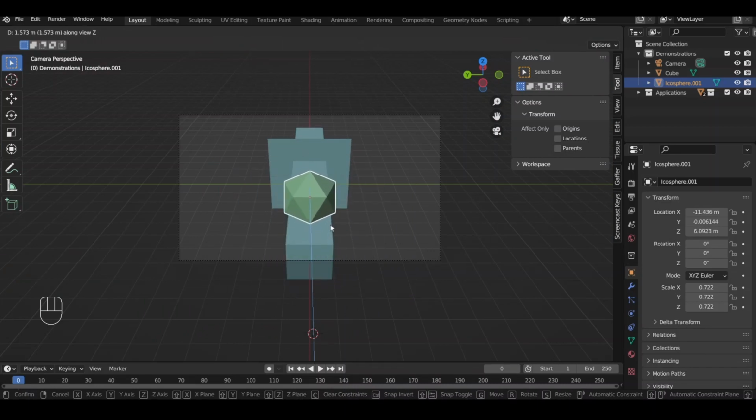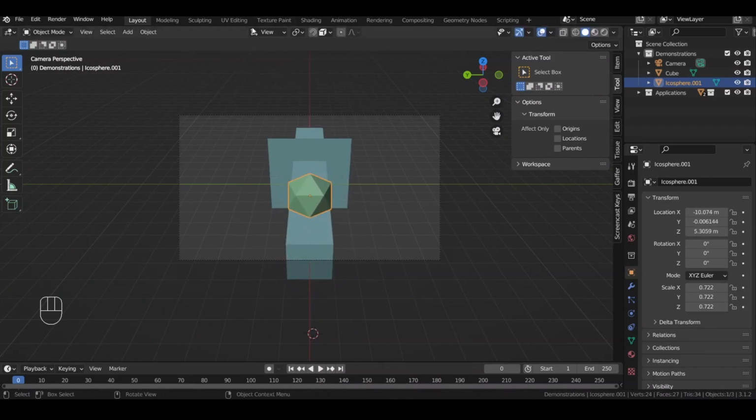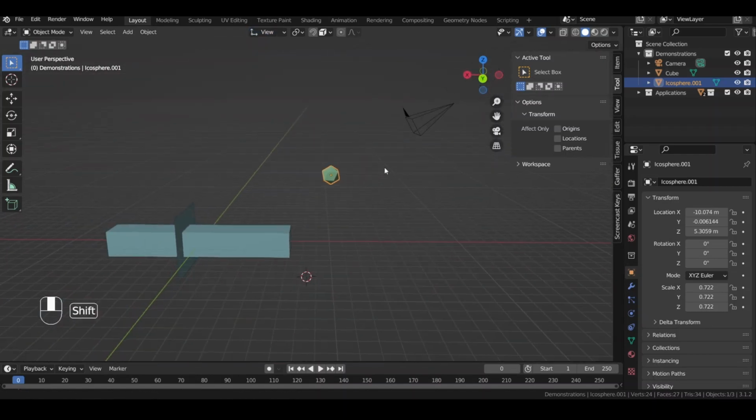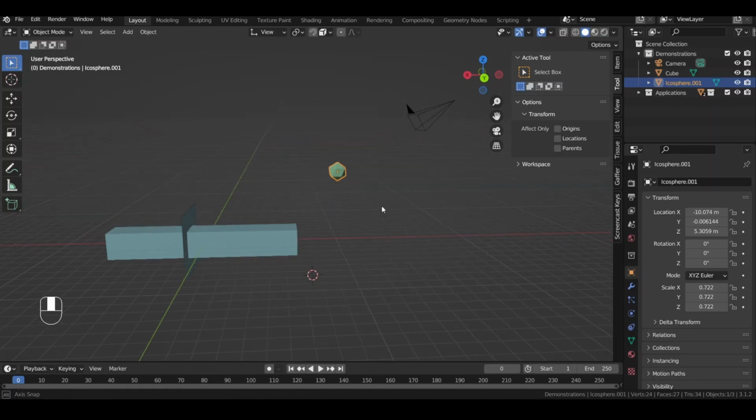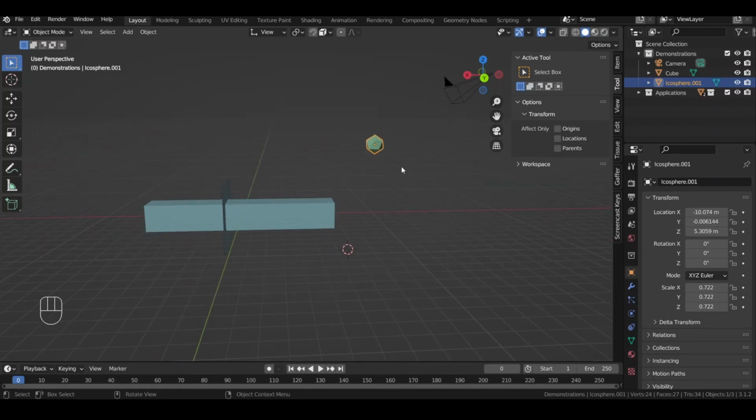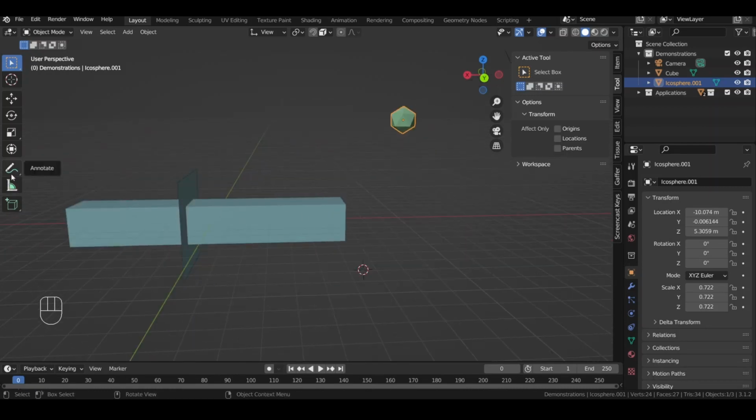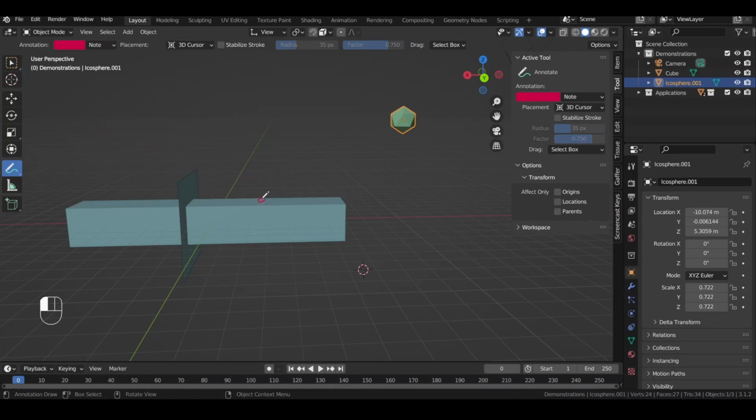It's the coordinates of your view space. And so snapping to volume takes care of that depth for you. As I mentioned, how I like to imagine it is that it finds the first contact, the second contact, and it calculates the center, and it snaps your source object to that center.